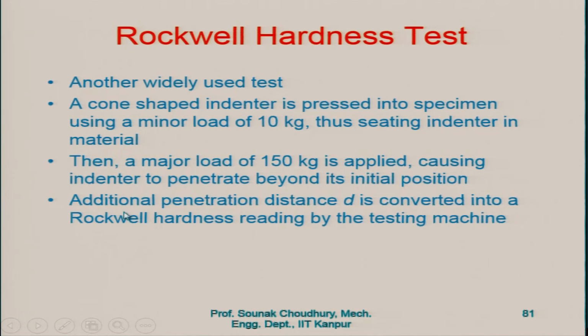The additional penetration distance d is converted into a Rockwell hardness reading by the testing machine. So, the cone shaped indenter is first pressed lightly with a load of, let us say, 10 kilogram, making a mark.